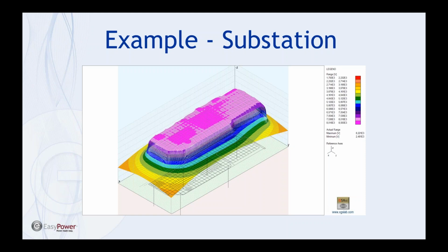And so even though the voltage is about 8,000 volts on this equipotential plane, there are minimal potential differences on the plane. If somebody's standing on this touching something, or taking a step on here, it's apparent that they're most likely safe. This isn't the diagram we use to determine safety, but it shows what the grid does, what we're building, and what happens during a fault.